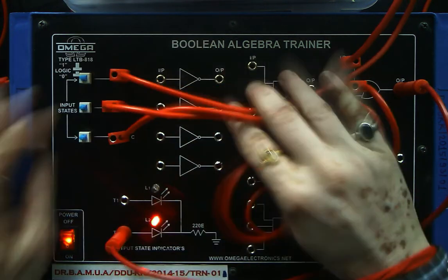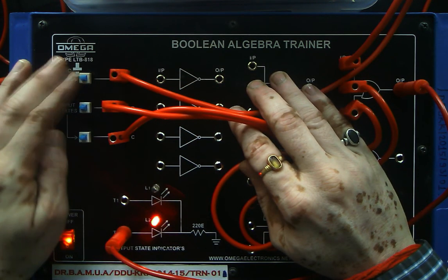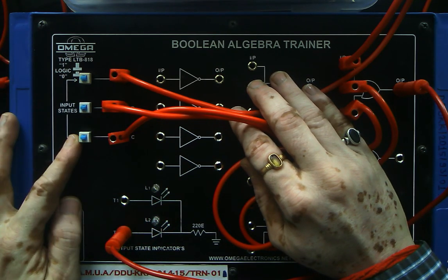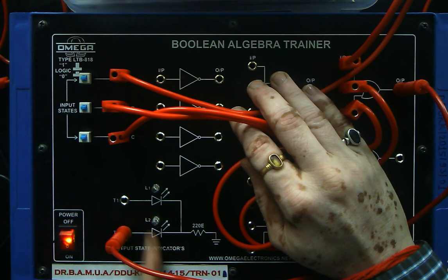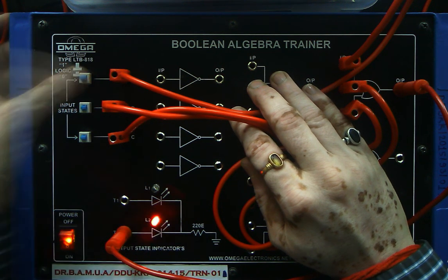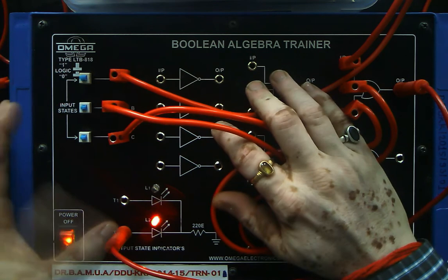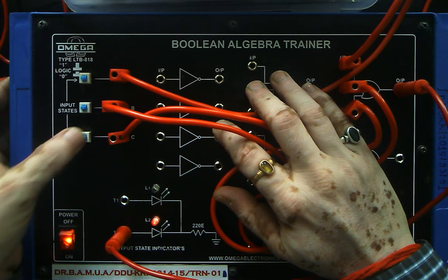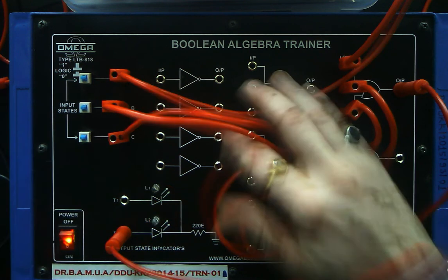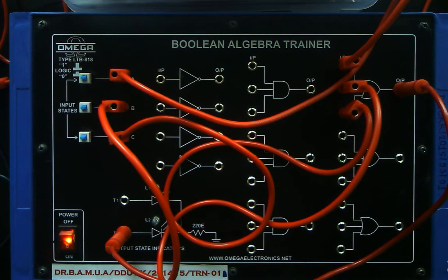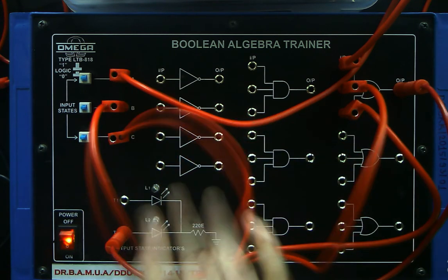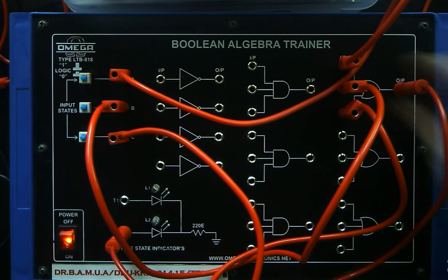So we can see over here that all the inputs right now are at logic low. I have pressed the switches, they are at logic low, therefore you can see the output is low. If any of the inputs is high, you can see the output is high. I will make this high, you can see the output is high. I will make them high, you can see the output is high. So you can see that the OR is perfectly operating. Now what we have to do, we have to take a complement of this OR. We need a complement of this OR function.